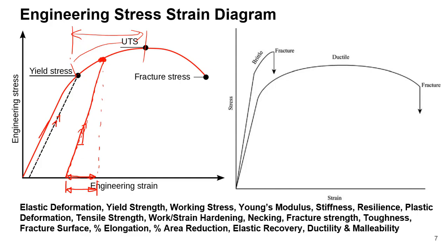But you can see that this portion of deformation is a permanent deformation, or plastic deformation. So this much is recovered, but if it is in the plastic region, then even after withdrawing the external load, it will come back along this line. That means a permanent deformation is still there. So that is why this is called the plastic deformation.